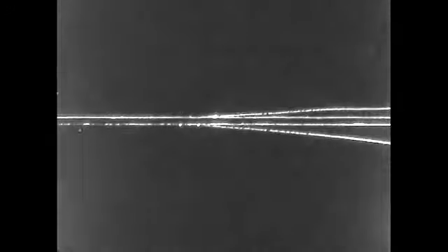To see why a turbulent boundary layer can withstand a larger unfavorable pressure gradient without separating, we shall again examine the flow along a flat plate. The boundary layer on the bottom side is laminar and two-dimensional. On the top side, the boundary layer has been tripped by a wire placed well upstream.